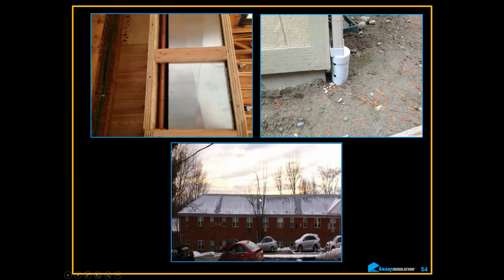This is separation walls right here. This is an older building. Separation walls have to be sealed for air and fire. They have to be. It's a requirement. These are not sealed. So when Mrs. Jones is playing the drums over here and Mr. Smith is listening to it, he's not a happy camper because the sound's just traveling right through the air spaces. What about a fire? Not good. What about cooking? Someone's cooking with a wok on this side with a lot of steam and a lot of oil coming out of it. I mean, do they smell it on this side? I bet they do. So again, just different examples of critical details.